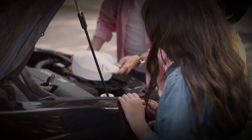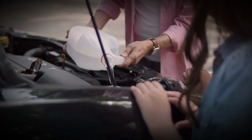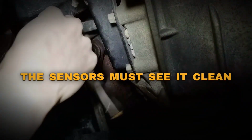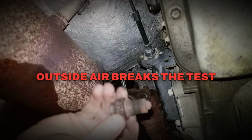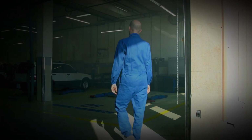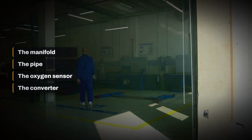Once the evidence is protected, inspect the part of the system that can change what both oxygen sensors see. Check 2. Look for exhaust leaks. The catalyst monitor depends on the exhaust stream reaching the sensors in a predictable condition. Outside air entering through a leak can make that information unreliable. Begin with the exhaust completely cool. Never touch a hot manifold, pipe, oxygen sensor, or catalytic converter.